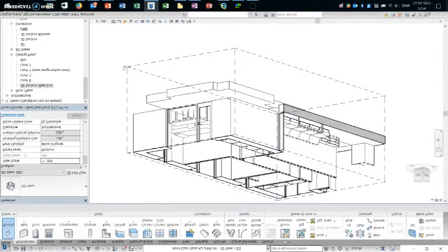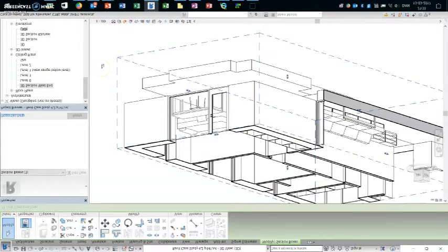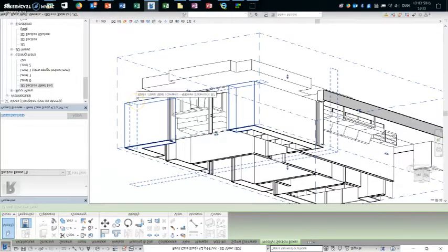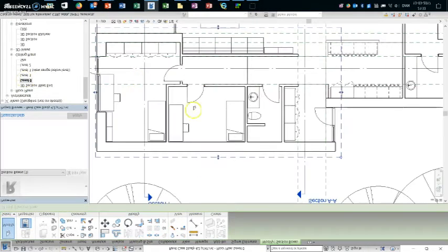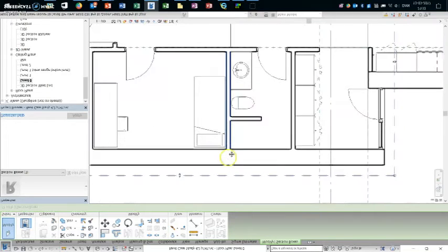Now when we go to our new section of the west end, we can see we've created 2 floors at different levels. So all we have to do now is attach the walls and windows, and then move the internal furniture to our new level. We start by going to level 0, and then we actually have to split this wall because the foundation underneath has to be different on this side and on this side.